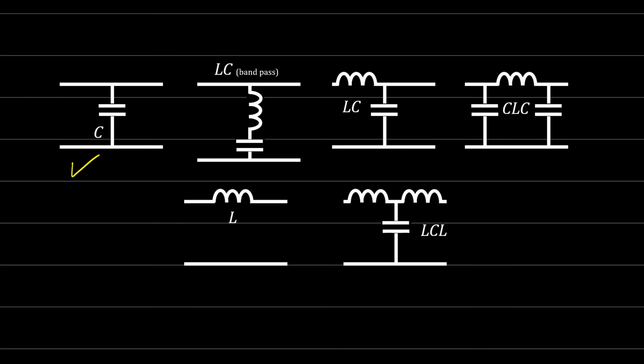You can eliminate only one frequency, or just a small band of frequencies. You can use an LC filter like this one, or you can use a CLC filter like this one. This filter can reduce the harmonics over a wide bandwidth, but it draws less reactive power.